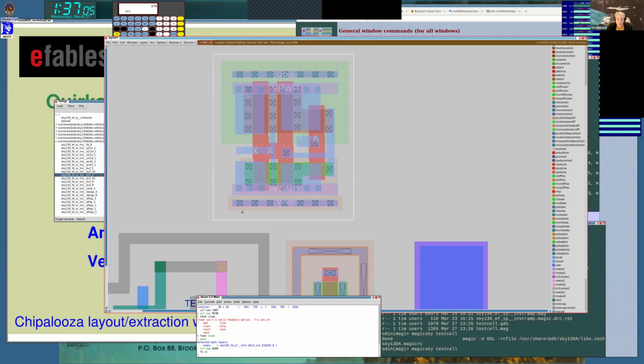That is definitely true of standard cells, because standard cells are designed just right so that all these cells can abut directly right at the edges, and there are all these layers that have to match across the boundaries from one standard cell to another.